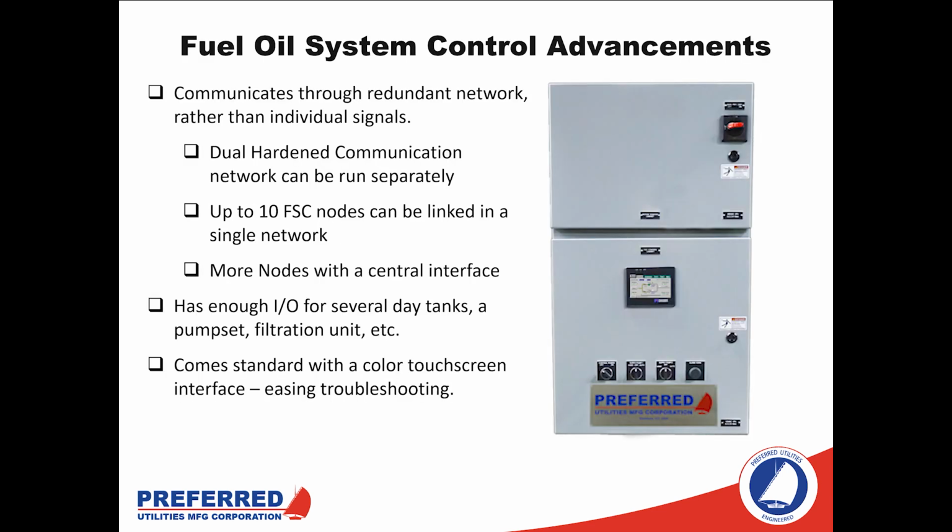There have been many advancements in fuel system control. So our historical system would have been a relay-based panel. A more modern system would have a microprocessor panel at the duplex pump set. But then pushing on into the future, we have many applications where peer-to-peer communication is also important. So we have an advanced system where the controls are not just located at the transfer pump set, but we have controls located at day tanks, at main tanks, at the polishing skid, and they're going to all talk to each other through a redundant controls network.